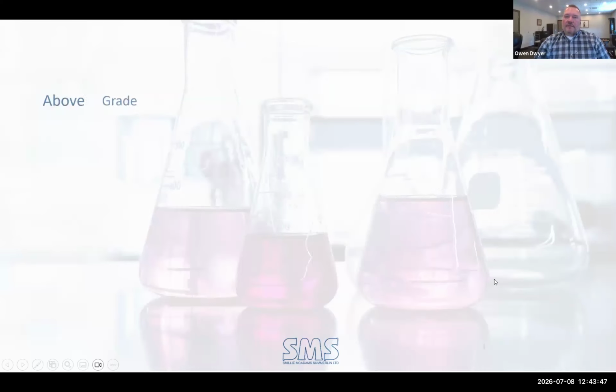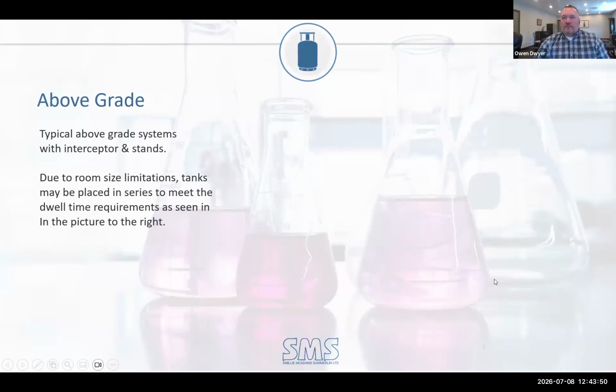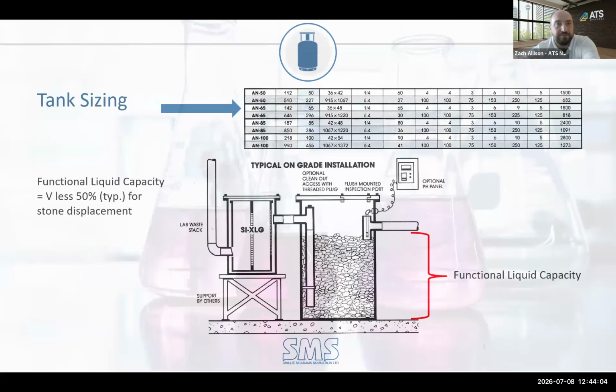So again, that dip tube that you mentioned is probably one of the most critical components. You talked about the laminar flow. The most critical element that we use to size this is the retention time, 1 gallon per hour per fixture unit. If you go straight across, you're not getting the retention time which is required in order to neutralize the flow. It's the same reason that you don't want to undersize it. So that is absolutely one of the most critical components, and you're 100% right, it is not necessarily called out in every spec.